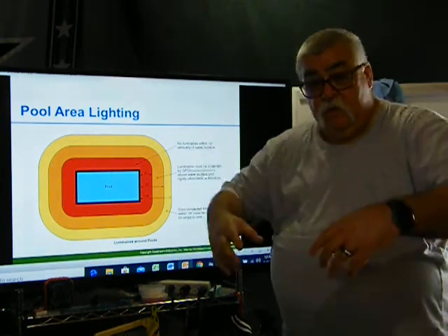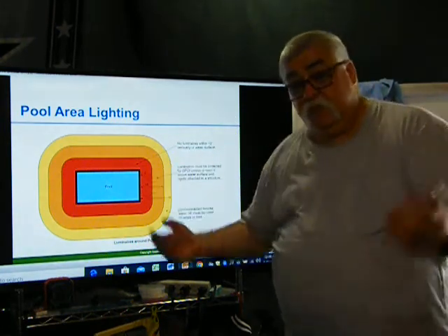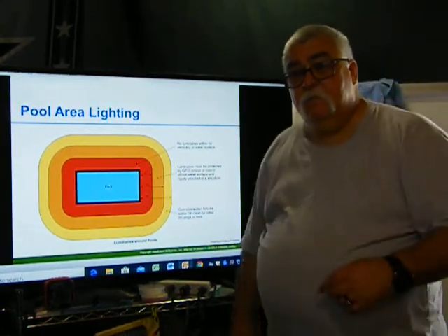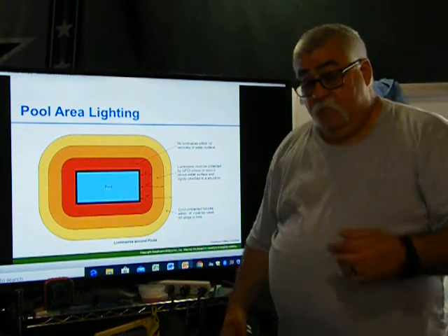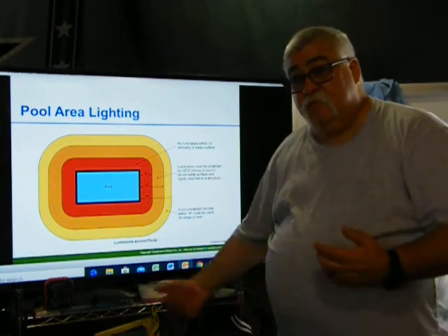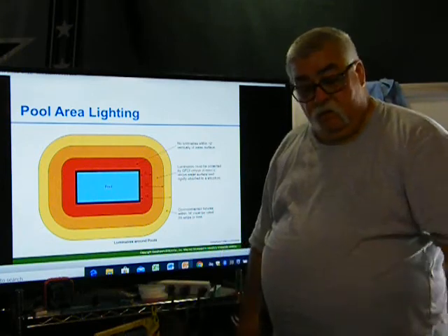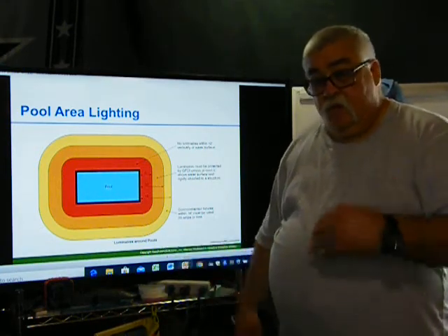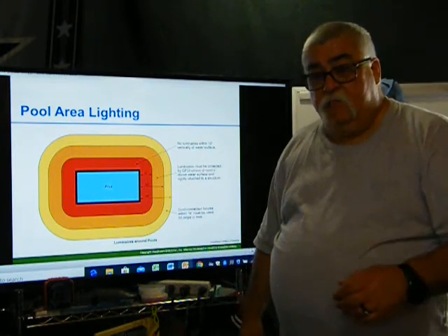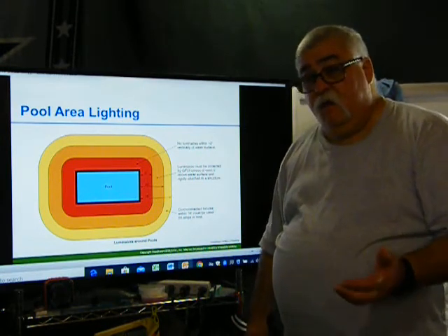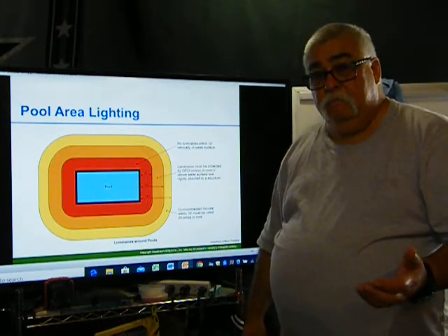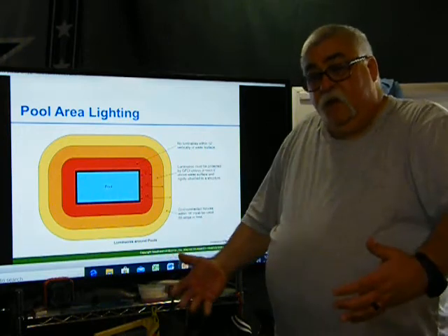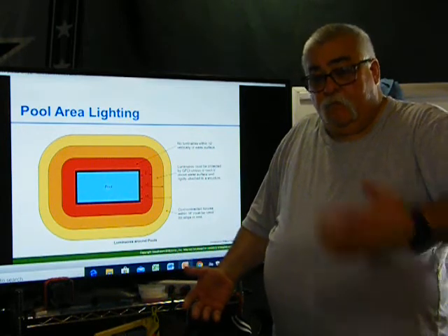So, if I'm in the pool and I'm adding, let's just go something simple, 1 amp. Okay? How many milliamps is that? 1 amp's 1,000 milliamps. We read earlier in the book, in the safety section, that above 50 milliamps, death is possible. You get above 500 milliamps, death is likely. Okay, well, this is not shocking you where you're shocked, but what happens is it paralyzes your muscles. And then you just sink to the bottom.